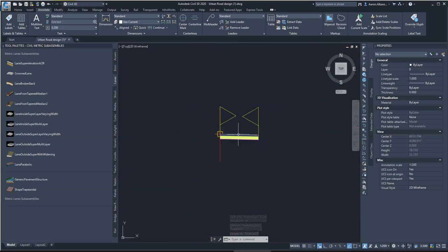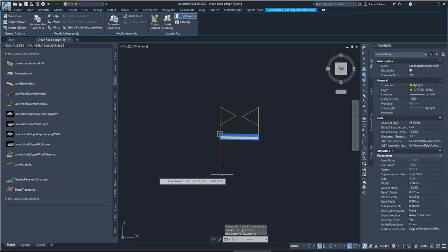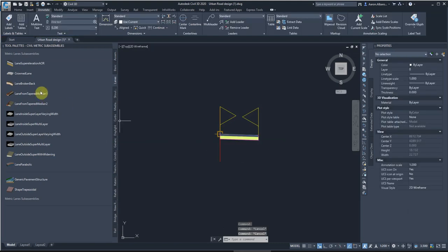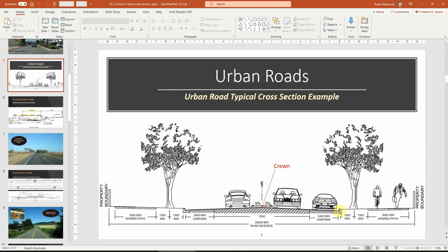So let's start with the basics. I added the lane, that's at 3.6. Let's keep it at -3 crossfall as what we've done before. You can always come back and change -3, -2. I'm not sure about the other videos when I created the intersection what the crossfall was on those, but you can easily come back to those, select the lanes and change the crossfall on them. The next component after the road, as we know, that would come straight away, the curb and gutter.